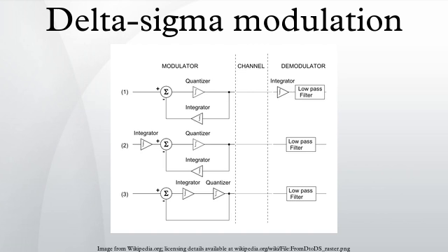On the right the input is now 0.4 of V and the sum during the impulse is 0.6 of V as opposed to 0.8 of V on the left. Thus the negative slope during the impulse is lower on the right than on the left. Also the sum is 0.4 of V on the right during the interval as opposed to 0.2 of V on the left. Thus the positive slope outside the impulse is higher on the right than on the left.